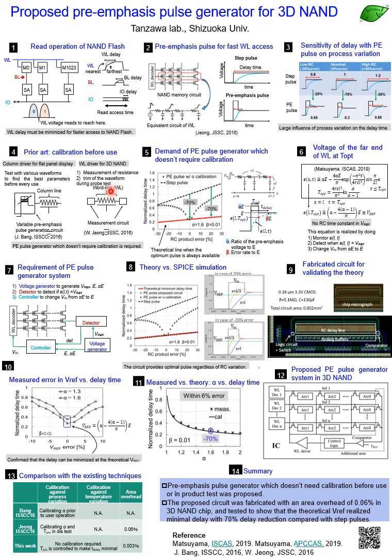They place dummy blocks next to the array and measure the resistance value of that dummy block during the probe test. So every single die is measured for word line resistance value.